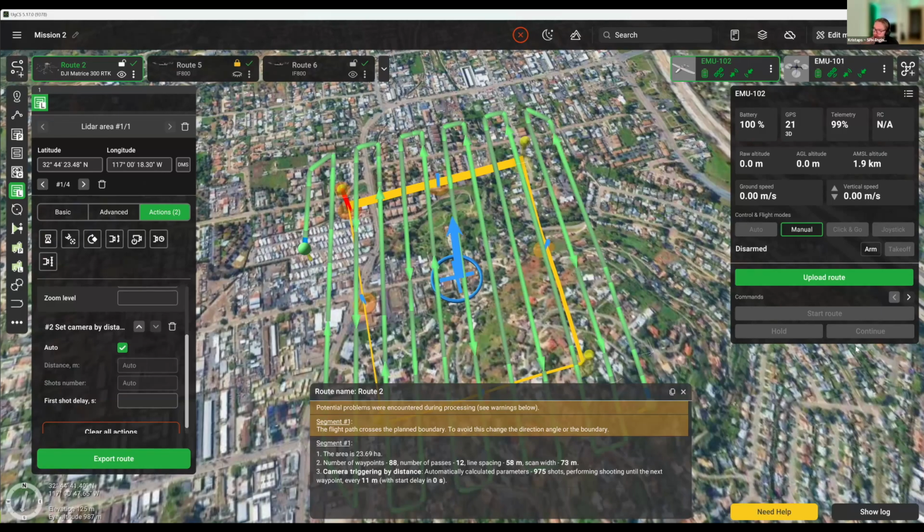So my guess is that you can try the U-shape. The Astro might be a bit better at that, since it would calibrate the IMU by flying forward and backward rapidly. So in case you have issues with pattern 8, you can try the U-shape and see if that gives better results.